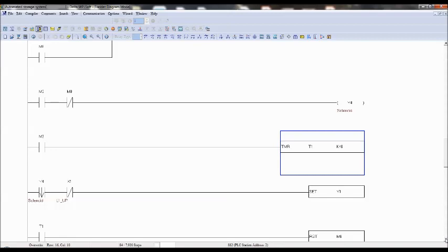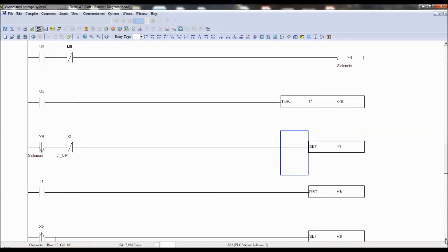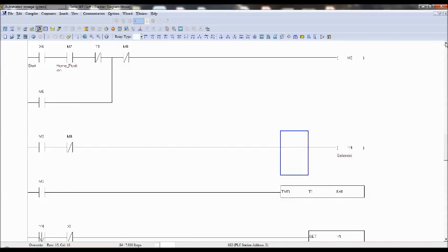That means solenoid should be off, right? So what I'll do is, see here after T1. See, T1 is here. After 4 seconds, I'll break the circuit so that M3 will be off. Whenever M3 is off, solenoid is going off, because solenoid depends on M3.